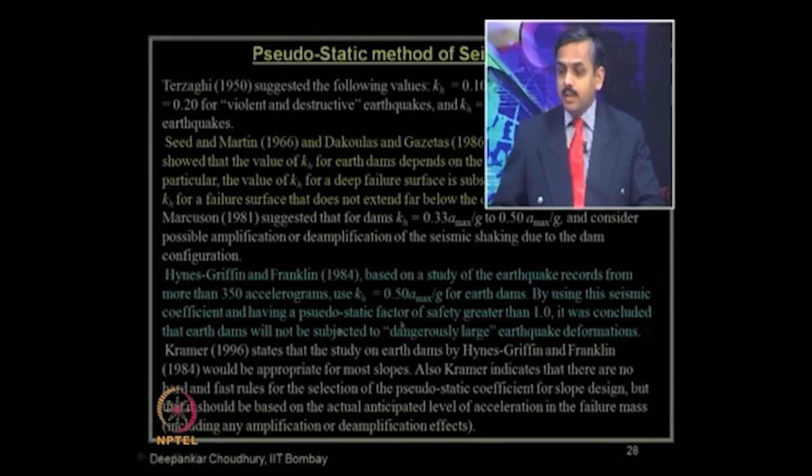But by using this seismic coefficient and having a pseudostatic factor of safety greater than 1, it was concluded that earth dams will not be subjected to dangerously large earthquake deformation based on their analysis, based on only this limited 350 accelerogram data. Remember that.